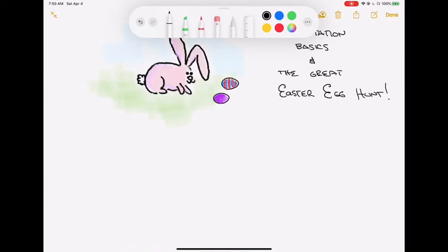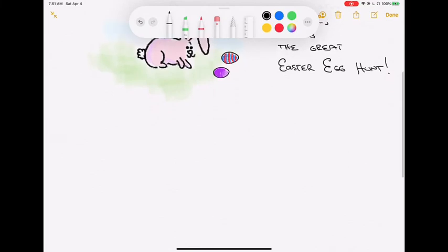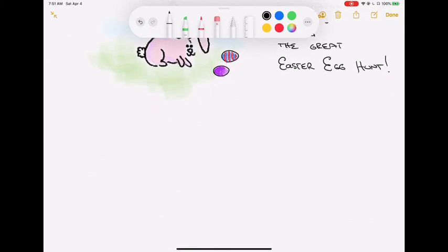These block structures are actually probably more directly useful to discrete time systems than they were for continuous time. The reason is that with most computing technologies, whether it's an embedded system or a computer, we can directly implement those block structures. We don't need to go through something like an op-amp circuit. So all we have to do to implement discrete time systems is get these block diagrams. They'll have the same sort of advantages and limitations and range of options available that we saw for continuous time systems as well.